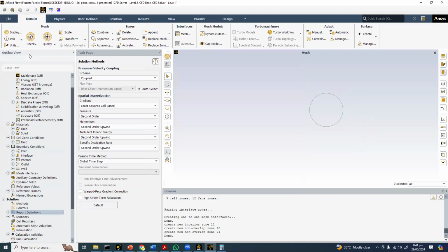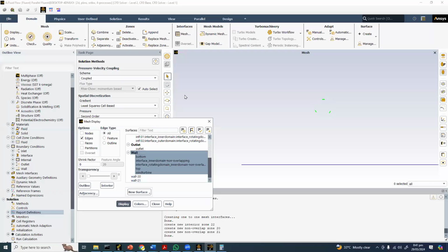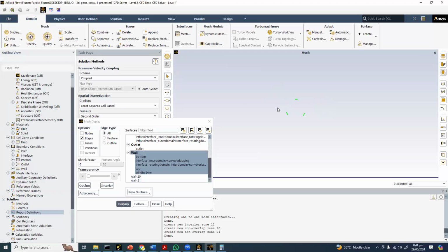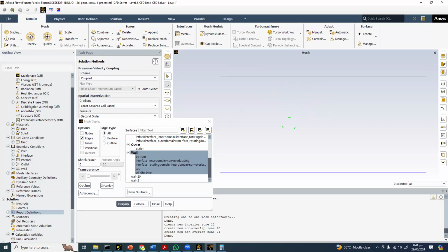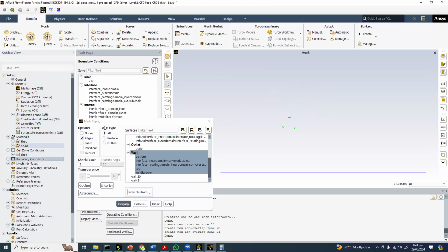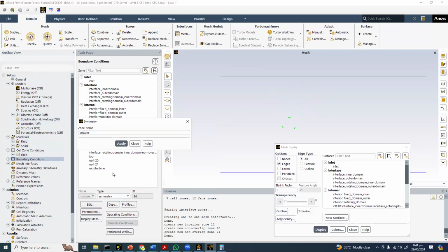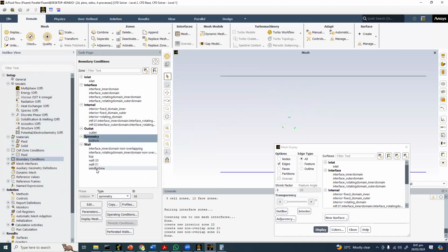Okay, then you have to make the outside boundaries the interfaces. They are not going to form any boundary layer, so these boundaries will be either no-slip conditions or symmetry conditions. So I have to change these boundary types from wall to either the slip condition, slip wall, or the symmetry boundary condition. So in the boundary conditions, the bottom will be symmetry. It's your choice. Symmetry with the slip condition is the same as a symmetry boundary condition. So the top.